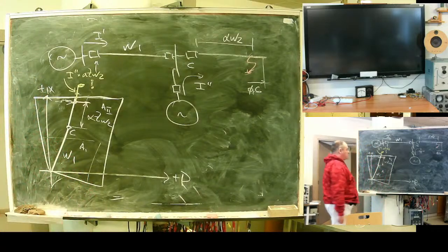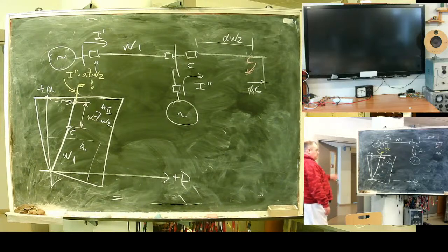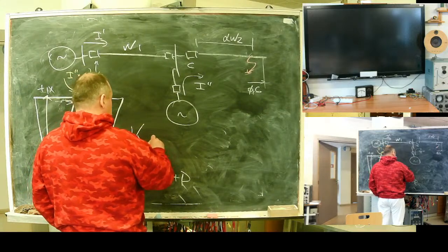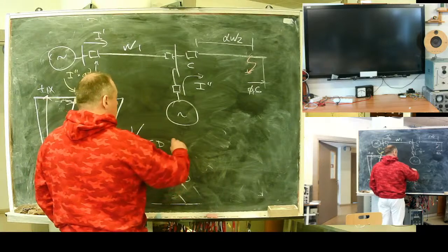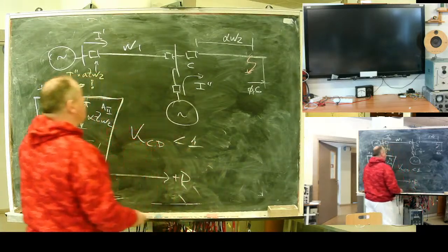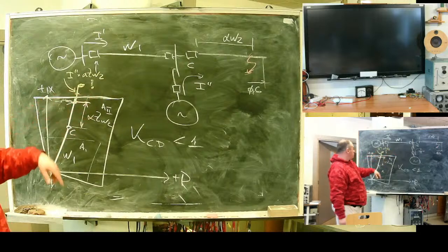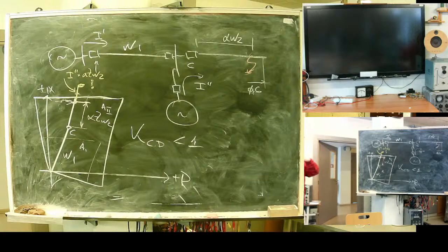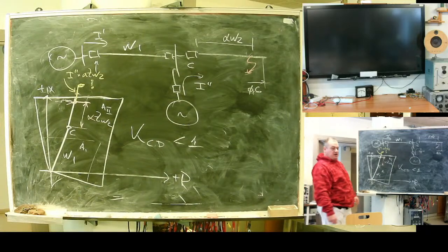Current distribution factor is the ratio between the fault current and the current seen by my relay, so it's the current of the relay divided by the fault current. Here I have this current distribution factor ZA less than 1. Only part of the fault current flows through my relay. This causes faults in second zone to appear in third. This causes delayed backup operation.